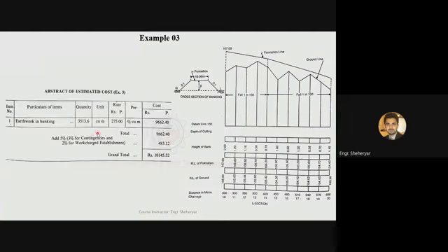After getting the total volume of earthwork, if you know the rate of the earthwork, then you can simply calculate the total cost of the earthwork. So the rate of earthwork is given here as 275 rupees per 100 cubic meters. Per 100 cubic meters, but the quantity of earthwork we have calculated is in cubic meters. So you must make both of these values compatible before multiplying them.